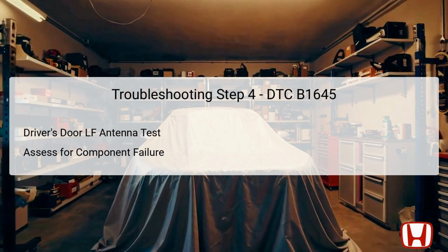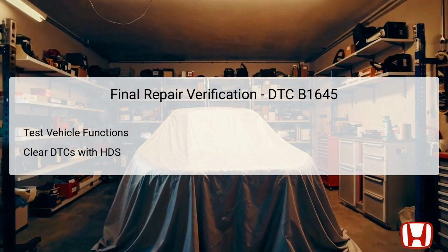by Honda. If the driver door LF antenna fails this inspection, it's an indication that replacement is necessary to restore proper functionality. Proper diagnosis of the antenna is key, as it directly affects the vehicle's ability to process keyless entry signals. After repairs have been performed, it's essential to conduct a final verification to ensure everything is functioning correctly.